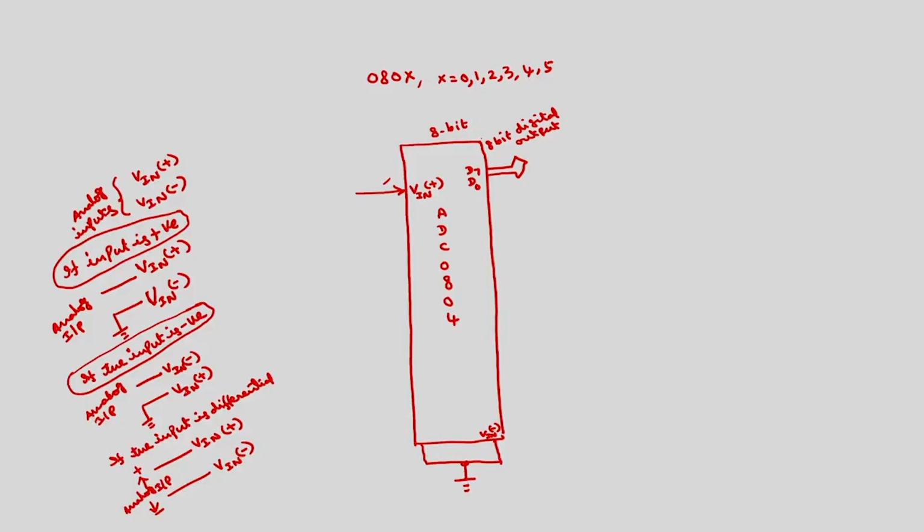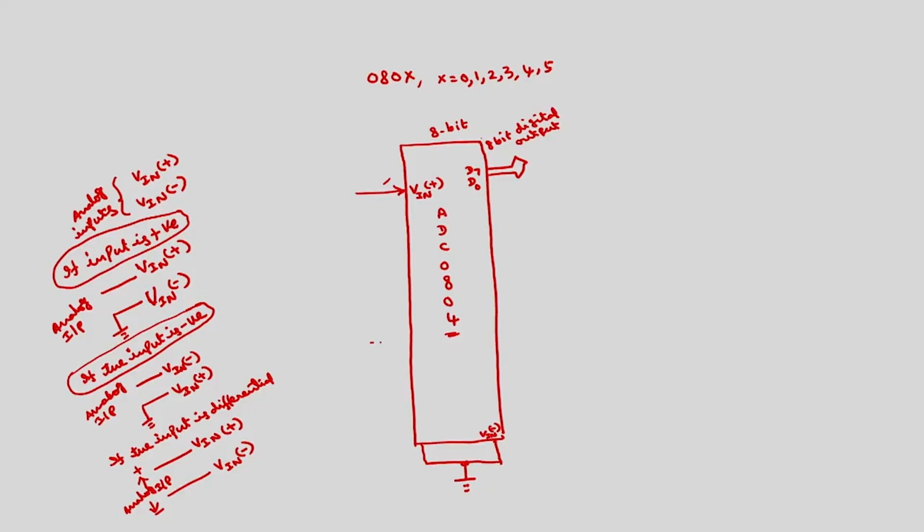Then in addition to this, the A to D converter requires some clock. The time taken to convert this analog signal to digital signal is decided by the clock. Clock has to be connected between two pins. One is called CLKR, and the other CLK in. You have to connect externally R and C, which decide the frequency of this clock.